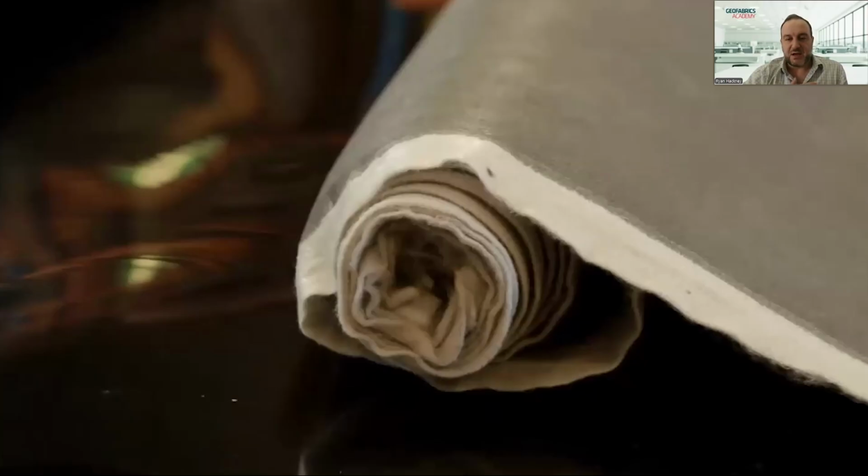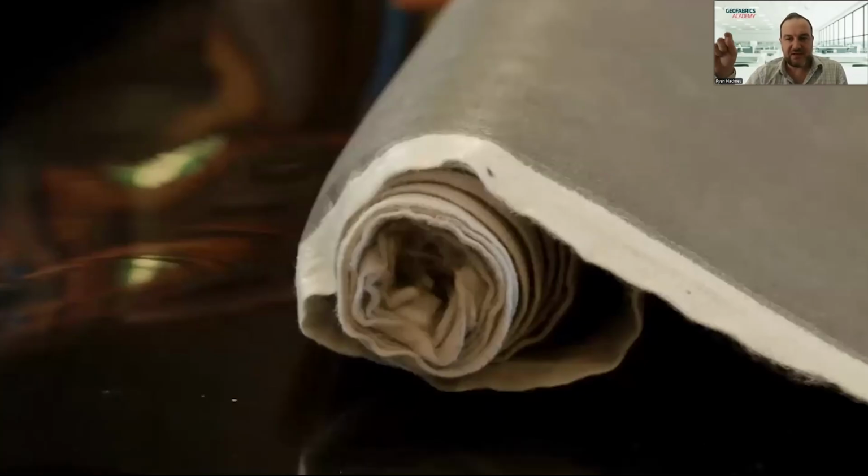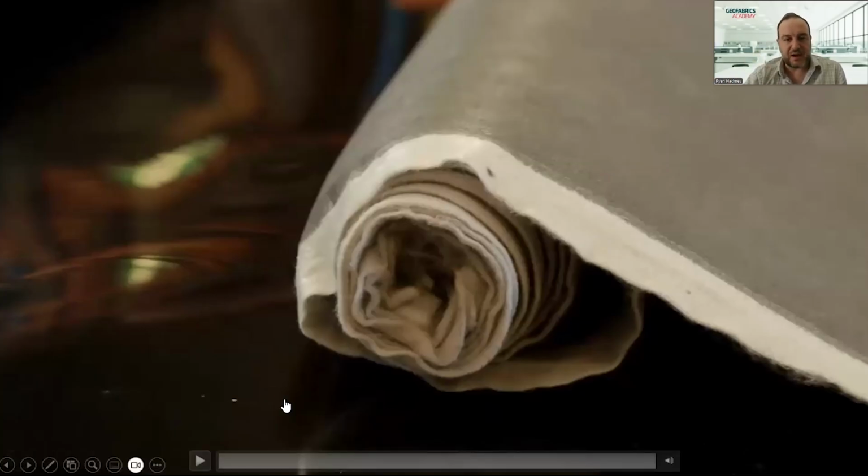So there's a non-conductive geomembrane on the underside, conductive geotextile placed in the middle, and then a non-conductive HDPE geomembrane placed on top. And that geomembrane has got a number of predetermined holes drilled in there, 5 millimeters, 4, 3, 2, 1, and it just shows how the arcing occurs through the defects onto the conductive geotextile in the middle.